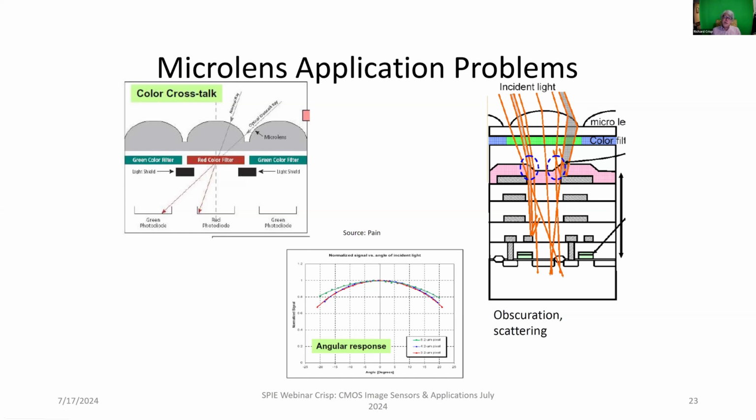And it can be really difficult, particularly for the pixels that are off axis, pretty far on the image sensor. It can create problems getting the light down to the pixel. And on very sharp, very fast lenses with a steep chief ray angle, you can actually get optical crosstalk, where light that should be under the red filter ends up getting sensed by the green pixels. So that can also be improved by having backside illumination.